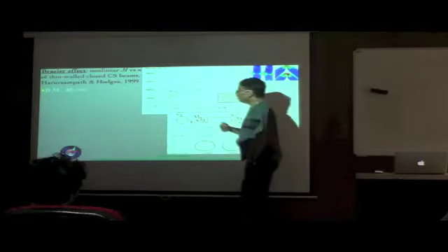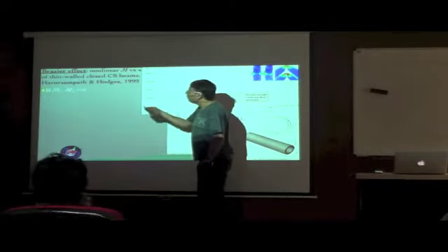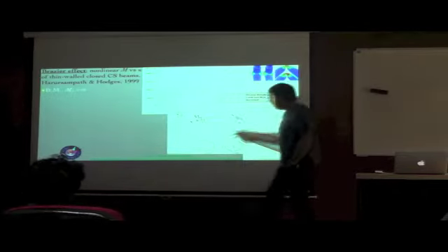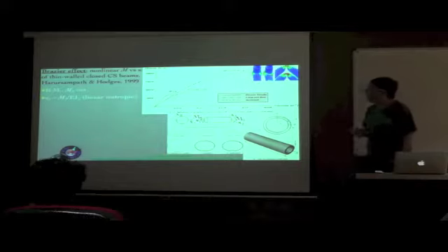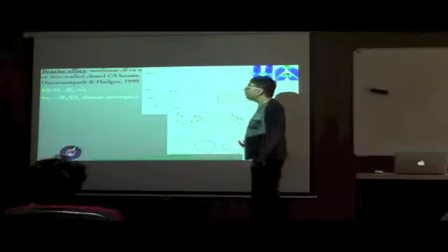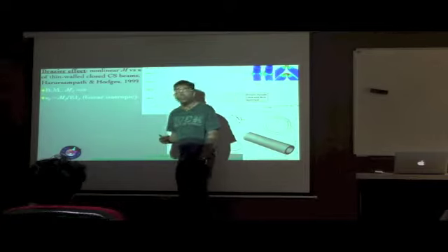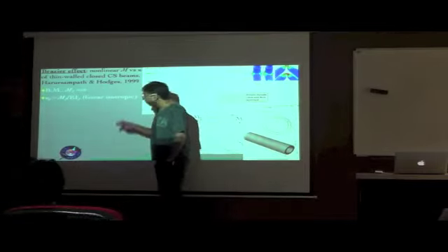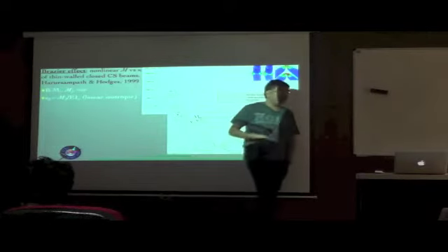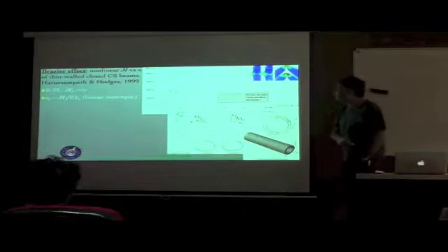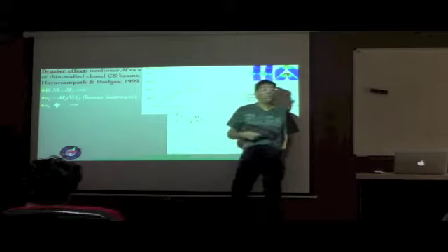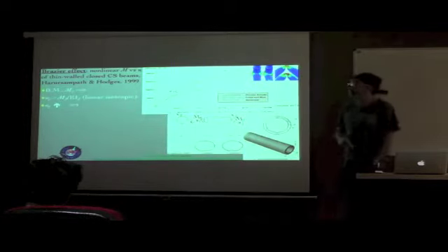So first of all, what happens is, in a mathematical sense, you are applying a load because of which there is a bending moment, and that is about the x2 direction over here. When that happens, the primary result that you end up with is the curvature about the 2 direction. Of course, in a linear isotropic prismatic beam, it just becomes M2 by EI2. It's a little more complex when you have more couplings. You'll have other kinds of deformation combined as well. And as you keep increasing M2, your kappa 2 will increase. That is this curvature about the x2 direction.